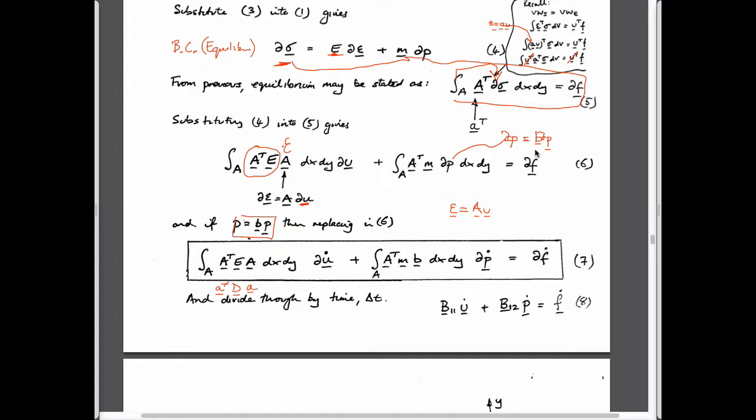And once we make the substitution, we have pressure included here. Then all I've done is take the derivative of each of those terms by looking at the time rate of change, in other words d/dt. That's what this expression results from. If you want to boil it down to something more concrete, we have a term here which operates on displacements, a term here that operates on fluid pressures, and a term here that operates on forces. Instead of being displacements and forces, they're rates of change of each of these, and of fluid pressures. These individual matrices which link these are made up like this.